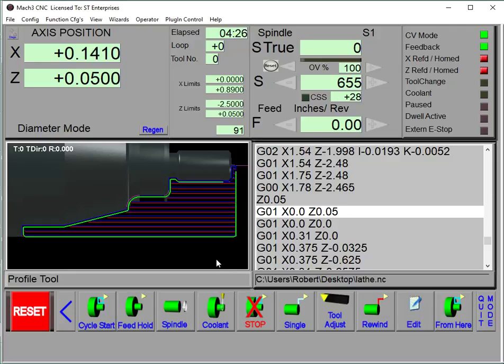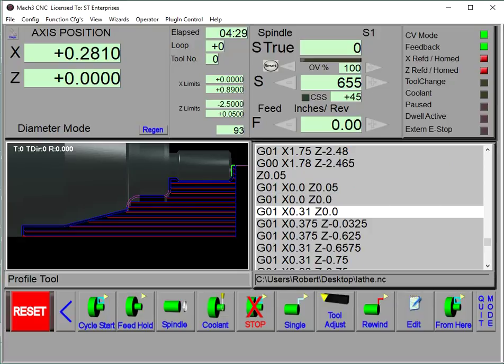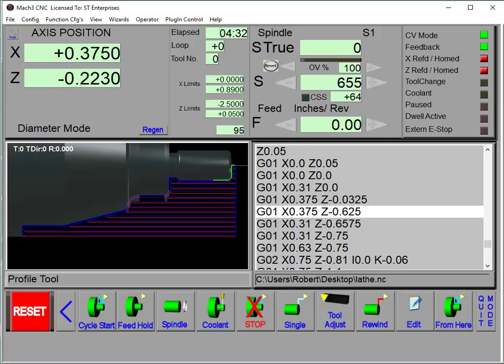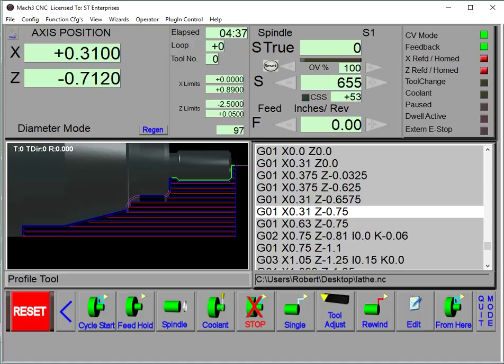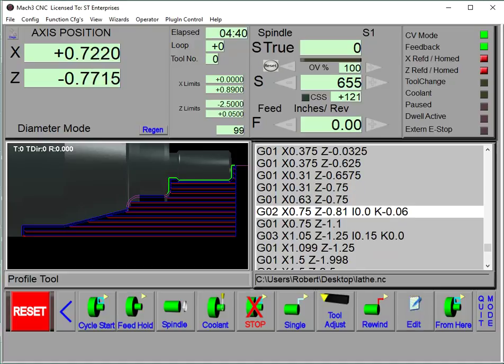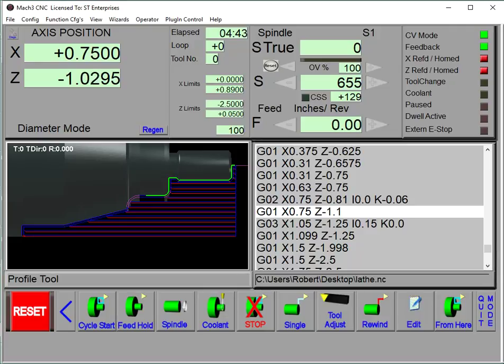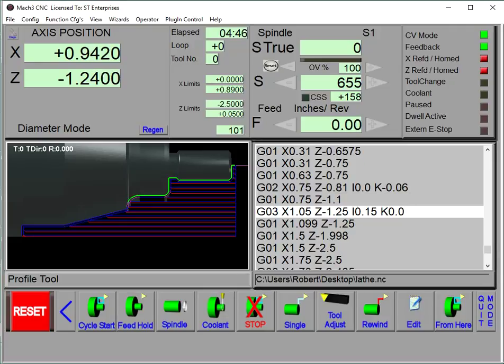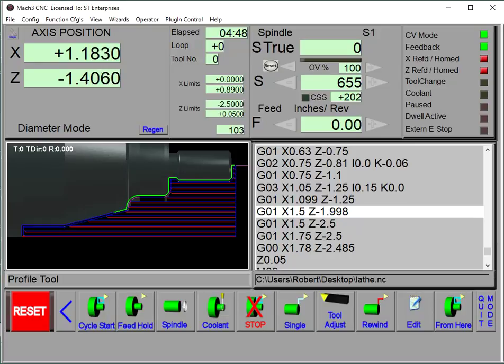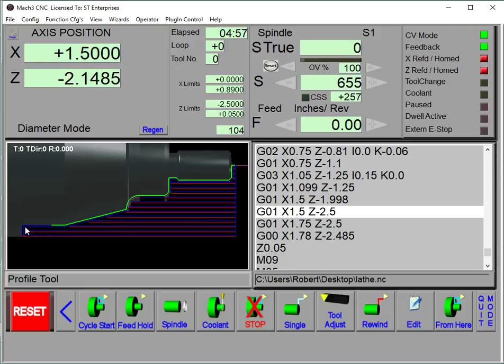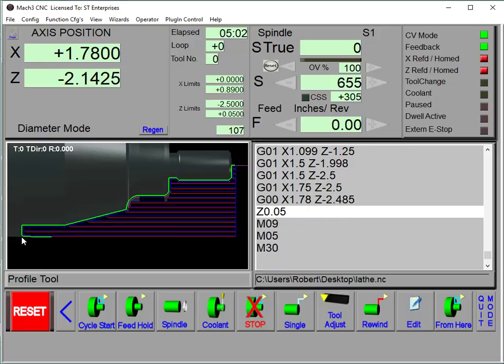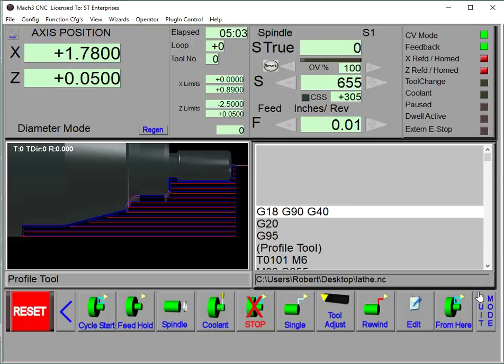Okay, now here comes the finished pass. There's the lead in, 45 degrees, and another 45 degrees. Now, finish radius, finish diameter, finish fillet, finish angle, and the finish diameter of 1.5 right there. And then this finish diameter coming up, well, it isn't finished, but that's the roughing diameter right there. Well, that's it. The part is done.